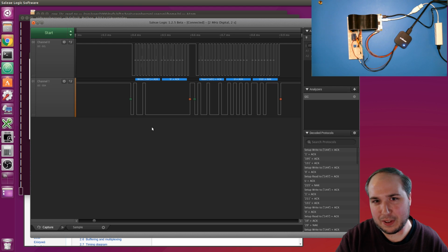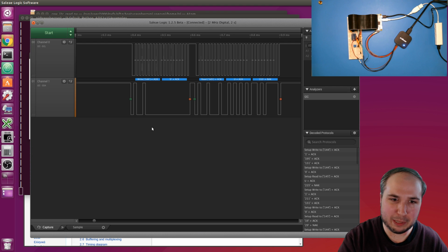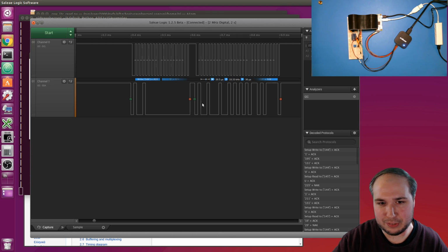And this comes down to the protocol that the device wants to understand. To talk to this ADC and pull a value from it, you first have to write a byte that says, okay, now switch to the actual ADC output, which is register 0. And then we're going to do some reads after this. And so now we can see another I2C transaction starts right after this one.